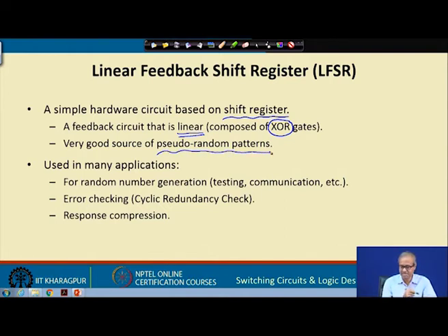And talking about applications, not only for testing, there are many other applications where this LFSR is used, for error checking using cyclic redundancy check, later on for response compression or compaction, we shall see it later, there again LFSR will be used. For data communication applications where there can be errors, you can again use LFSR for error detection and stuff like that. Okay. So, there are many applications, but here we are interested in test pattern generation for the time being.